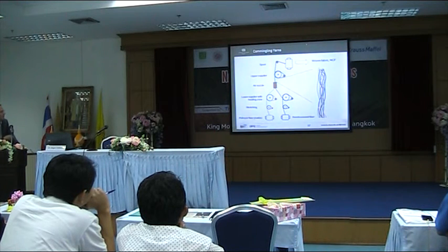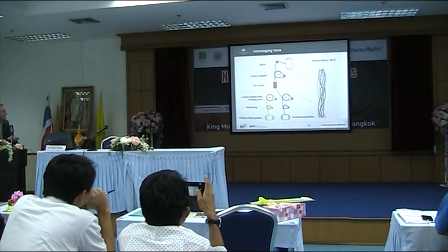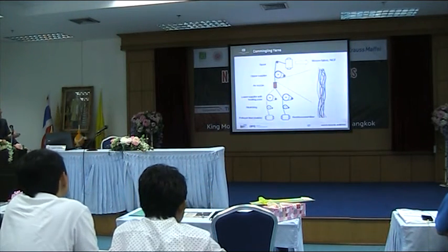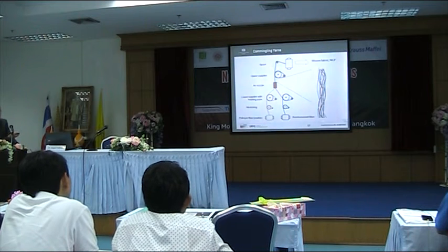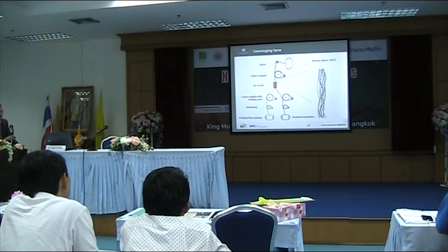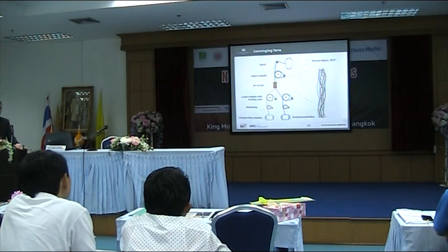Also typical is so-called commingling. We have the single fibers of the reinforcement fiber and polymer fibers, and you have an air nozzle and mix the fibers, so-called commingling. And then you have a hybrid yarn which consists already of the matrix and the reinforcement, and can then go into some textile process. Non-crimp fabrics can be made from it, but also woven fabrics are really popular.